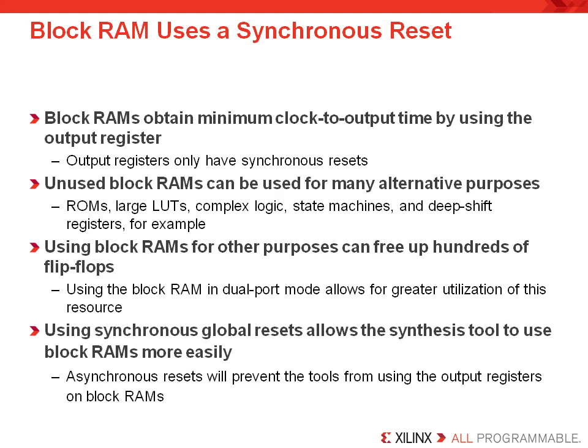But what designers don't realize is that, like the DSP slice, the block RAM does not allow inference of an asynchronous reset. This is because there is simply no asynchronous reset functionality built into the block memory. So to infer the block RAM's output register functionality, make sure you infer a synchronous reset.